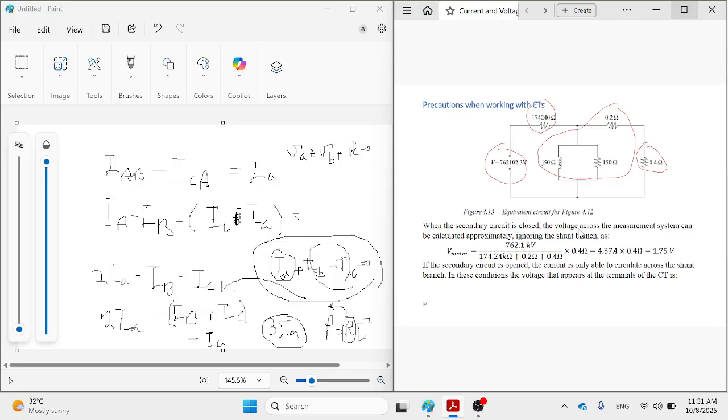Okay, you can simplify, but because these values you can ignore. If you want, you can calculate it in the correct way. Then you can see the voltage finally is something like this. So you can follow the correct way, which is this one in series, parallel with this one, parallel with this one, and then again we have it in series, correct? Or you can follow these techniques and say, okay, these two values are big and just ignore them.